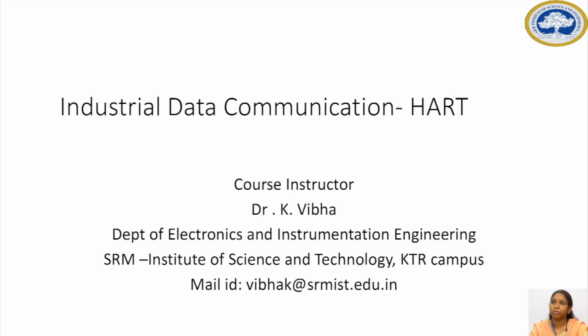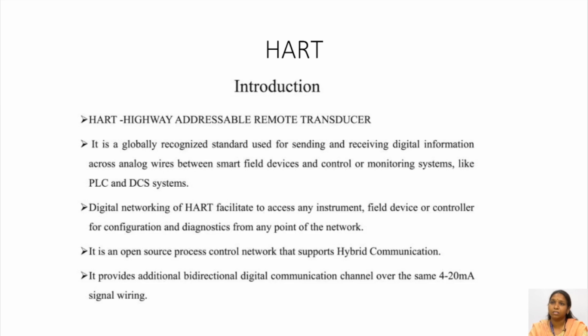Welcome, you all. Today we are going to see HART, which comes under the subject title Industrial Data Communication. What is HART? HART is Highway Addressable Remote Transducer. It is a globally recognized standard used for sending and receiving digital information across analog wires between smart field devices and control or monitoring systems like PLC and DCS systems.